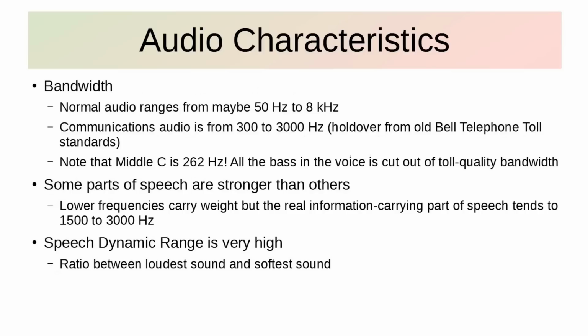A little bit about audio characteristics on single sideband. The bandwidth is not the full audio range of the human voice. The human voice ranges from maybe 50 hertz to 8-ish kilohertz. That'll cover both male and female. Female, you tend to have some of your fundamental carrying tones a little higher in frequency. Now, communications audio is from only 300 hertz to 3000 hertz.